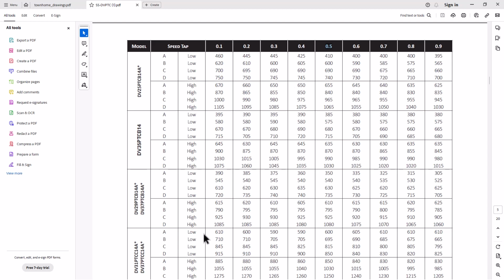However, since we're doing friction rate, we want to have enough static pressure to overcome dirty filters, elbows, and a lot of pressure losses. So most of the time we go to 0.7. Honestly, it's good to do it at 0.5, but let's be safe here with 0.7. For 0.7 we have two options, low and high. So what's the closest to my target CFM?